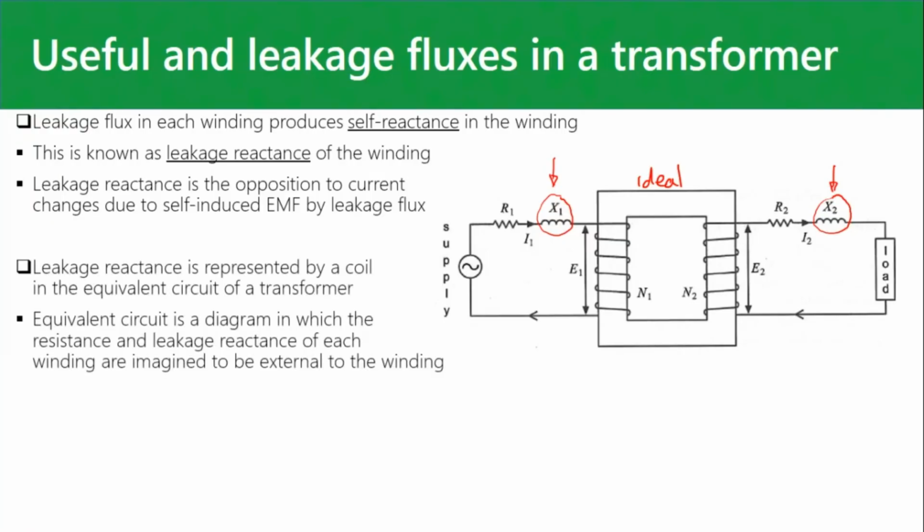So you also have resistance in these windings. It's small, but it's finite, and we have to take it into account. So in these windings over here, they have a finite resistance, so we model it there. Remember, we're assuming an ideal transformer here, so we model these imperfections, showing them as a resistance and an inductance, just to build up a model.